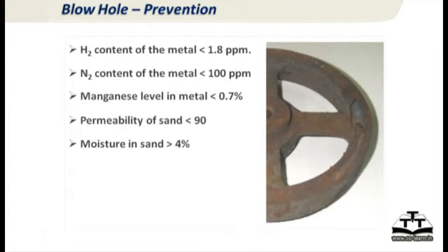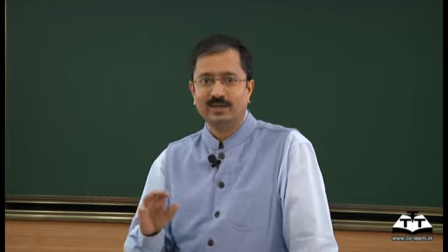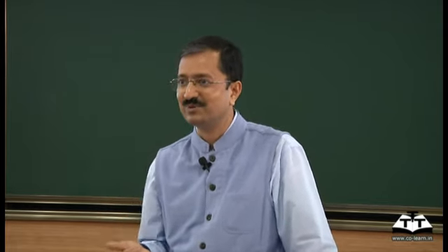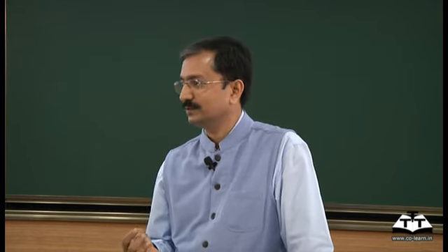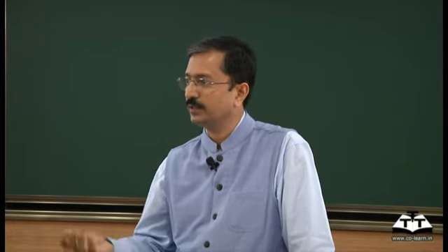Could be one, but then the gas generation is coming from so many sources, and oxide is only one of that. So if you have an induction furnace, and if you are in a dry season, obviously you see gas porosity jumping in monsoon seasons, right? Particularly in Indian foundries, the majority of the furnaces are oil fired. Cupola or oil fired, where you have hydrocarbons.